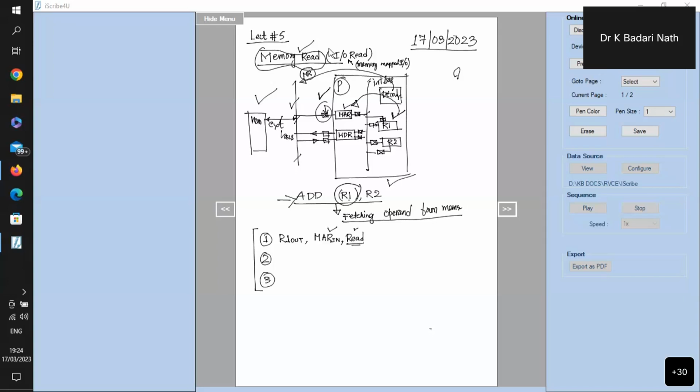That is why most processors have a signal available to the bus interface circuit. The signal is called wait for memory function complete, WMFC we call it. For example, in Intel processors, this pin is called the ready pin. So Intel provides a pin called ready. The external devices like memory and the slow devices will send 1 or 0 on the ready pin.